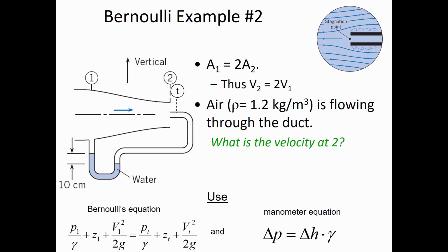In other words, the pressure here at location 1, inside the nozzle, since it's a gas, it's air inside the nozzle, what we're going to do, just to simplify things, is assume that the pressure at the center of that nozzle is the same as the pressure at the top of the water, because air pressure doesn't change very much vertically. That's a pretty good approximation, that the pressure at the center of the pipe is the same as the air pressure that's in contact with that water.